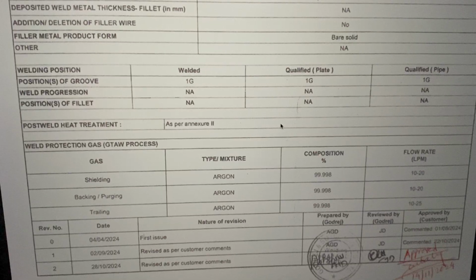And after that machining, if we are going to do any work or assembly, at that stage these stresses shall not relieve, or over a period of time the stresses shall not relieve, or if the job has a high temperature application, creep can get introduced and the stresses will become even worse. So it is good to think all that beforehand.